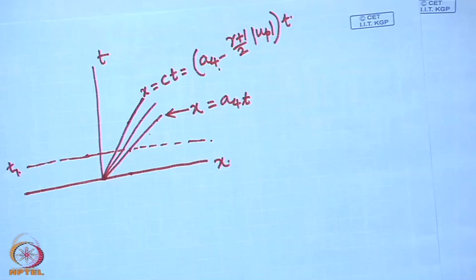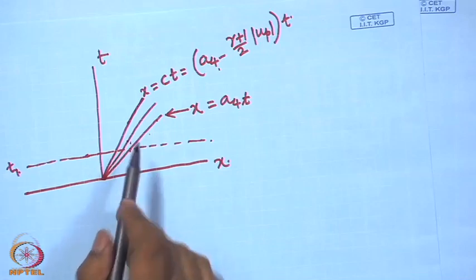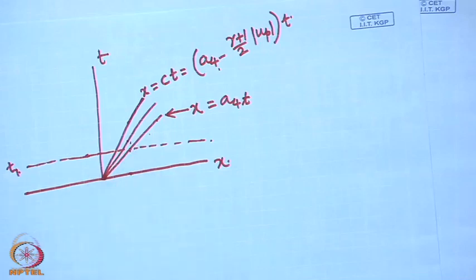Now, see that the wave speed decreases continuously, since u p, or the absolute value of u p, is positive of course, and it is minus u p. So, the wave speed continuously decreases. These fans of straight lines that we are showing here are lines of constant c and thus of constant u and rho.